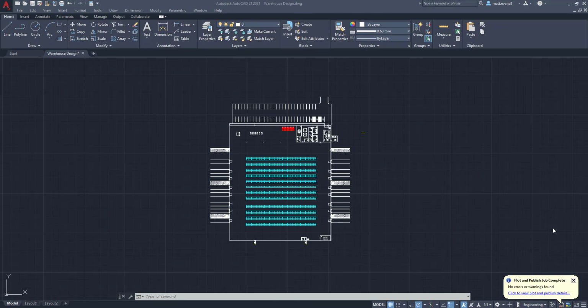All right, a little bit of a quicker video, I understand. Hopefully it got the point across. Hopefully you now understand what options you have for a DWG to PDF or AutoCAD to PDF. I personally always use the print one because I just assume that line weights for objects will be off, as they normally are. It's not a problem, but again, I use the print to export it to a PDF versus the just export button itself. Now again, if the export button's easier for you, please use that. Just adjust the line weights, but the print option's easier for me.